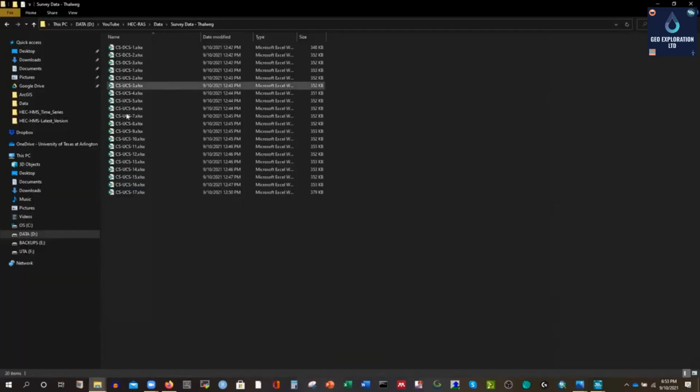So that's that. See, 17 means most upstream, and if you go to 1, it is close to the breeze. And then we have CSDS, right? We have CSDCS. This 1 means it is close to breeze, and 3 means it is away from the breeze, to the downstream. So this 3 means it is the most downstream, and the 17 means it is the most upstream. So our total number of cross sections is 20.